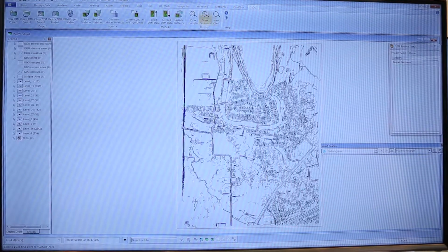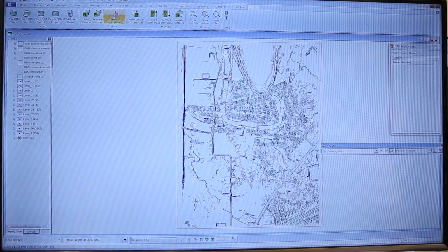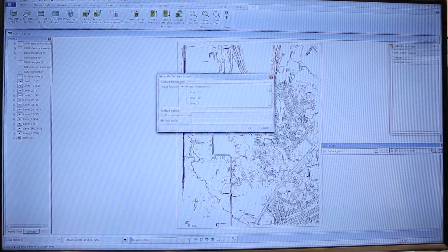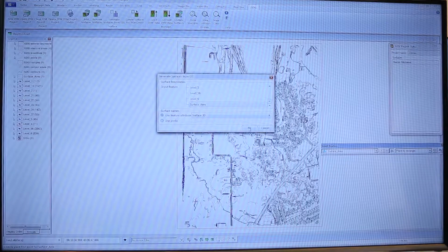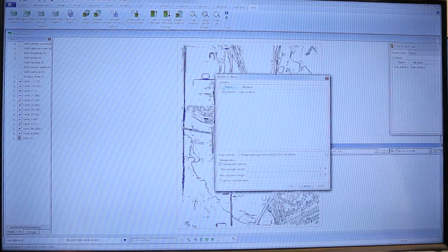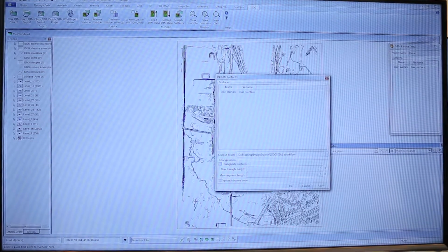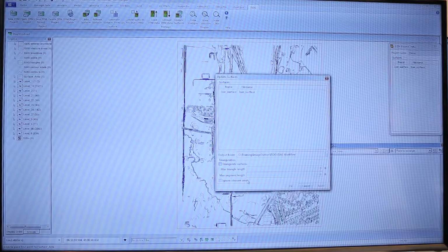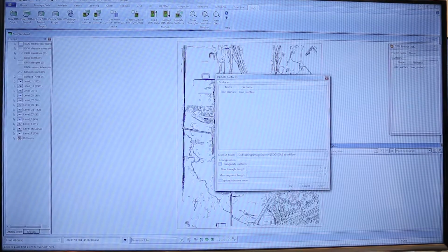Okay, now back in the ImageStation DTM for GeoMedia, we can create a new surface using that surface feature. And we'll load the breaklines and obscured area features into that. We don't need to triangulate or ignore the obscured areas at this time because we're just feeding that as input to our automatic elevations.